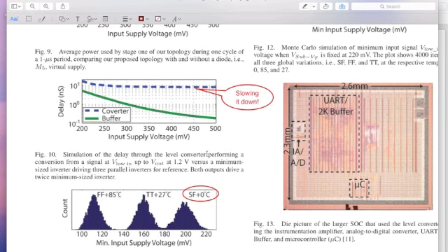PMOSs have to be stronger than you expect it to be. So it has to be a fast PMOS. What temperature will you use? For that you have to look at the dependence of threshold voltage on temperature. As you increase the temperature, threshold voltage reduces. That means if I want to weaken the NMOS, I have to increase the threshold voltage. That means I have to use the lowest possible temperature. So that is the worst case condition.